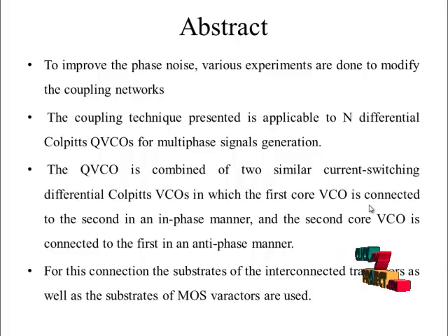first core VCO is coupled to the second in an in-phase manner, and the second core VCO is coupled to the substrate of cross-connected transistors as well as the substrates of MOS varactors, which alleviates the need of any extra elements for the coupling, which could add noise and increase power dissipation. A linear analysis is presented that confirms that the proposed circuit generates quadrature waveforms. The proposed coupling technique can be generalized to n differential Colpitts VCOs for multiphase signal generation.